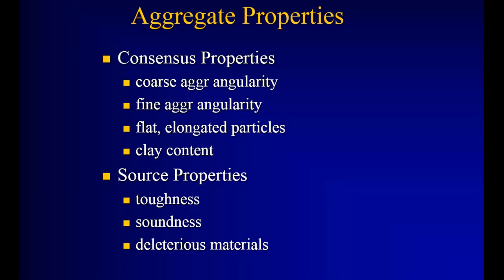All the plus 3/4 then went to the crushing operation. The crushing operation, any -4 that came off that crushing and screening operation with the scalped material was considered manufactured fines. But that was the only way. If it was scalped on a 1/2 inch screen, nada, 0 manufactured fines.